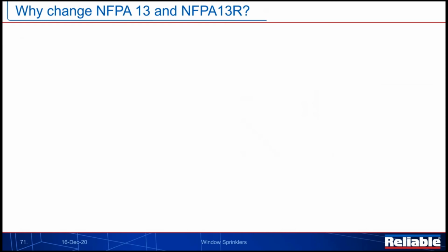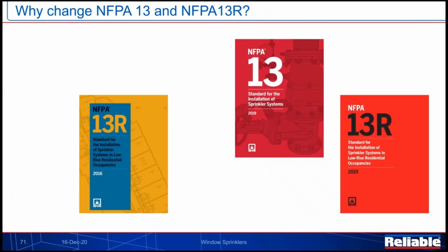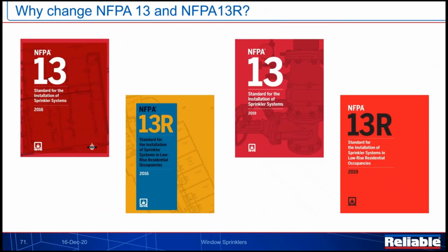So all those things from NFPA 13 take into account exactly what the ICC-ES was wanting to see, what UL was doing with their test criteria. It tries to roll it all up and put it into NFPA 13, something that's been adopted by the local municipality where this building is being built, and help tie everything all together. So IBC says what it needs to say.